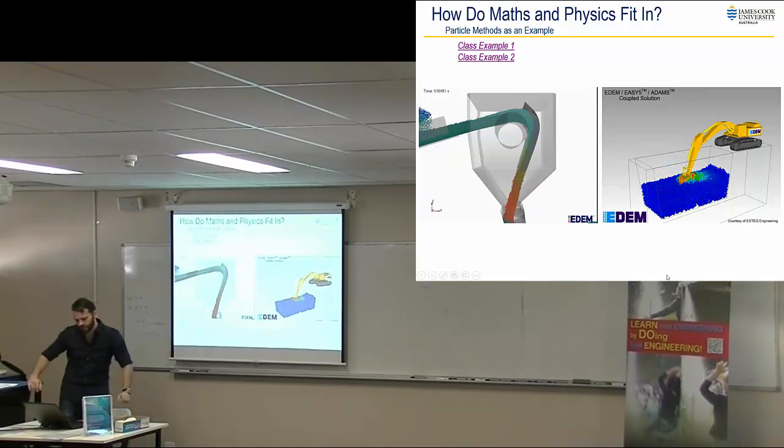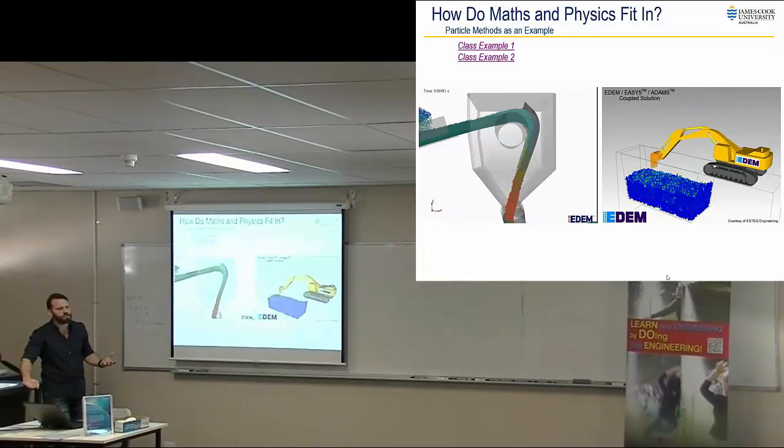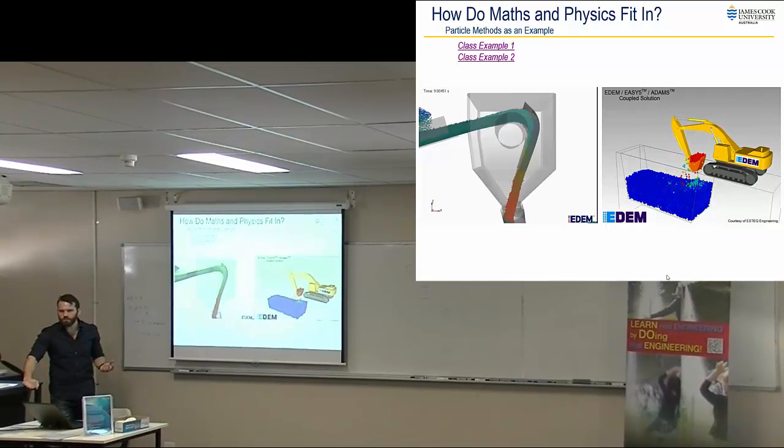And then here we got, and this one's definitely velocity. We've got an excavator bucket. You can see the faster they move, the redder they are. And obviously that's not very good excavation, but you can see the proof of concept, why you might actually do this. With excavator buckets, one of the biggest things with those is the amount of energy you need to cut through the materials for a particular excavator bucket geometry and how much wear you get on those excavator buckets.